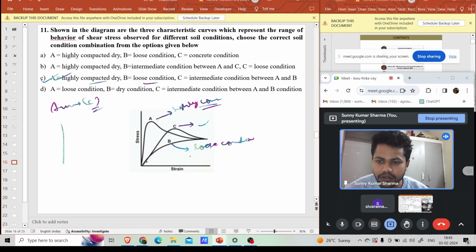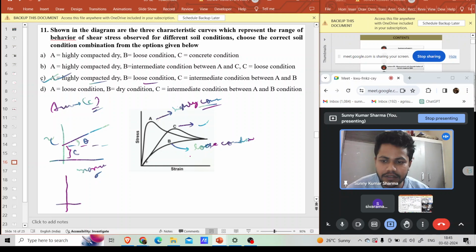And you can also relate it with this, which is normal stress. If we draw it as sigma versus tau, then we get this type of curve, which we have studied many times. This is the angle of internal friction phi, and this is cohesion C. And in case you can also relate it with, if this is W and this is the thrust developed by the soil, then this intercept is AC, and this is the same phi.